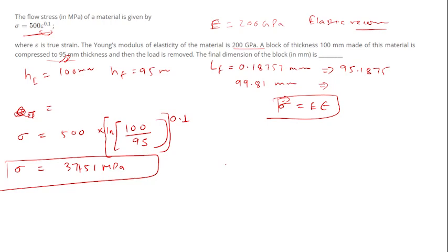Now from here we can calculate your strain. Now fill all these values in here. So it will be 371.5. Your E is in GPa, so we will convert it into MPa and simply write it as epsilon. What is your epsilon coming? Strain is 0.001857. It's fine, right?